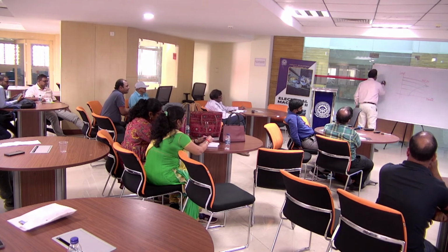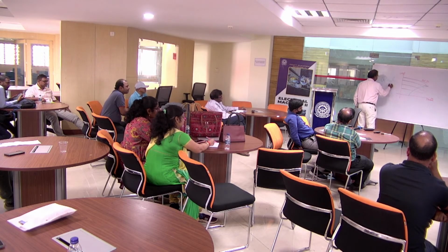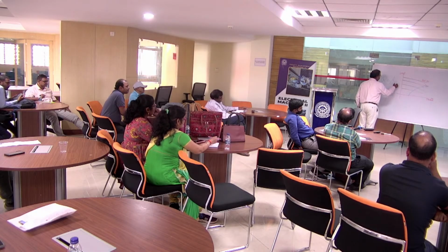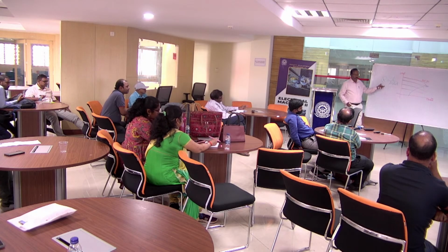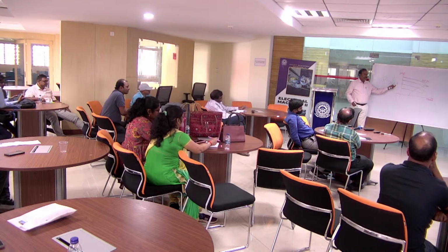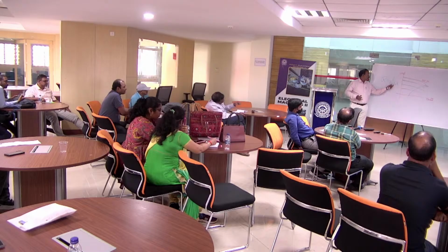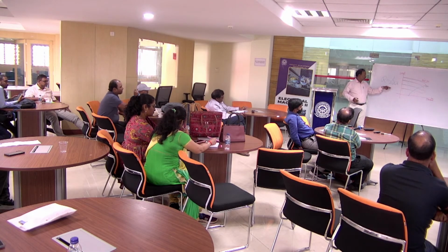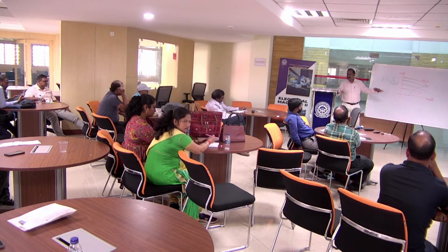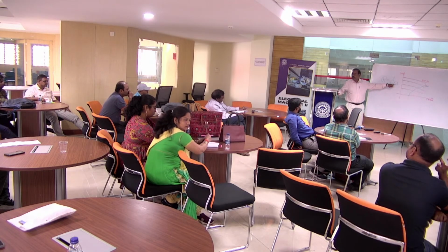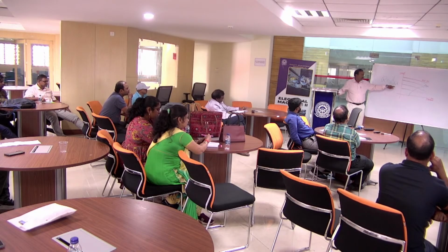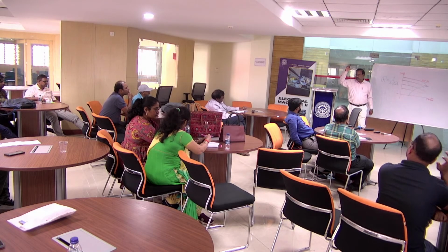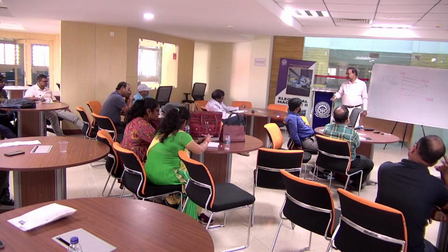I'm defining reluctance like resistance: l by mu 0 mu r A. For an iron core, this mu r is of the order of 1000, 10,000 like that. So reluctance is small. Compare with air, where mu r equals 1. Compared to air, the iron core has a reluctance lower by a factor of 10,000.